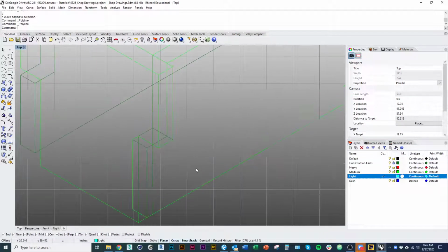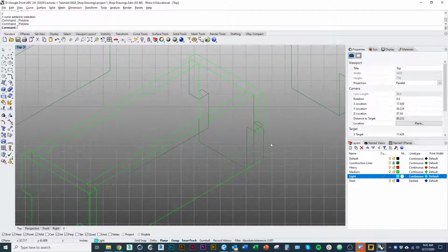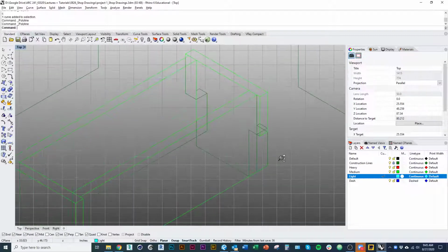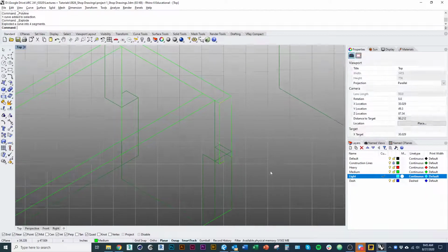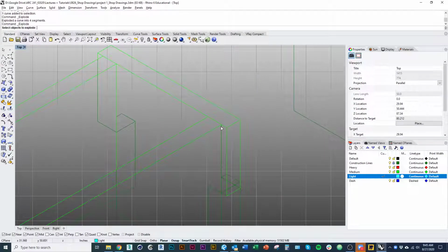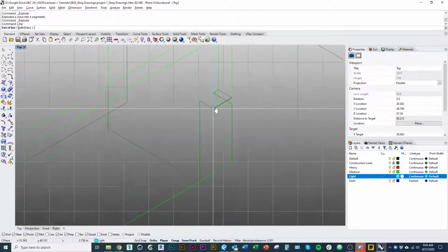And one thing that'll be important to do is line weight this drawing a little bit differently, because we want it to be understood in 3 dimensions, right? So we're following different rules. We're following the rules of axonometric drawing, where the profile line is actually the heaviest line weight, right? And so what we would do is some of these interior lines, and I might just explode them, I would start to draw those on a lighter line weight.